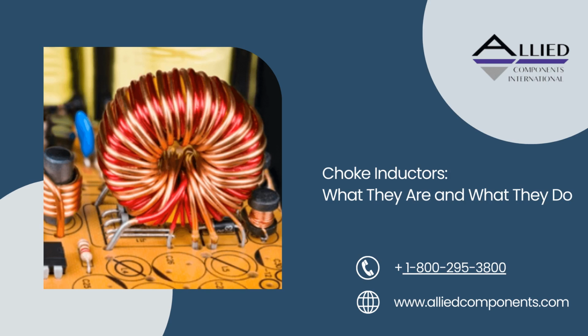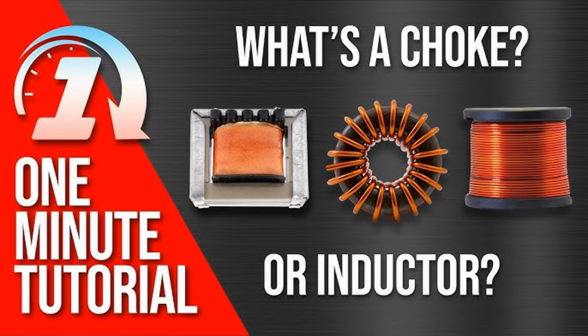Types of choke coils. Power choke. Used in power supplies to smooth out ripples in DC voltage. It helps in filtering out high-frequency AC components from the DC supply. Radio frequency, RF, choke. Designed to block radio frequencies while passing lower frequency signals. RF chokes are used in radios, communication systems, and other circuits dealing with radio frequency. Audio choke. Used in audio equipment to filter out high-frequency noise while passing audio signals.